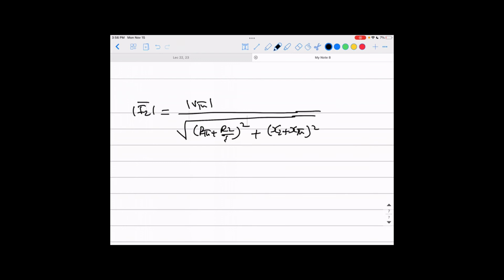And easy enough, we came all the way down to calculate the torque. Remember, torque equals P air gap over omega S, and you found it to be 3 times I2 magnitude squared times R2 over S, divided by omega S. We come here to find I2 as a magnitude and place it in this equation.